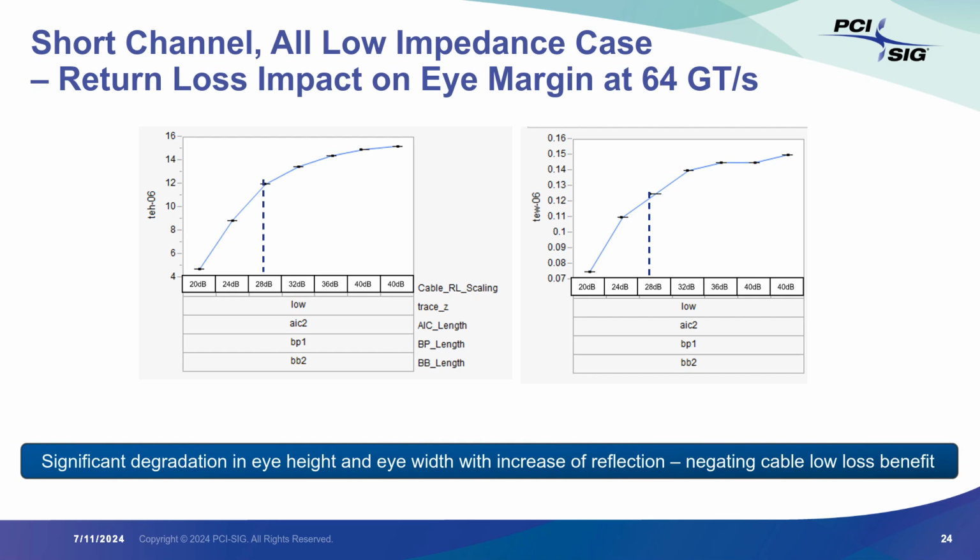So you can see that once we improve it, higher means better return loss, lower reflection, it starts saturating, which means that if you improve it or even make it reflection free, there are other channel components which then take over. You don't get benefit from this cable component.